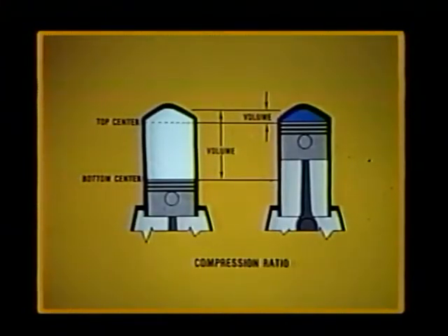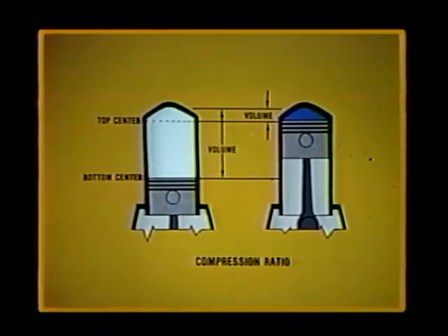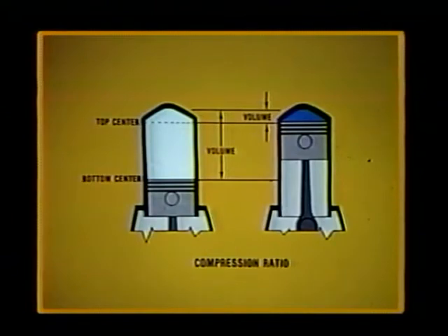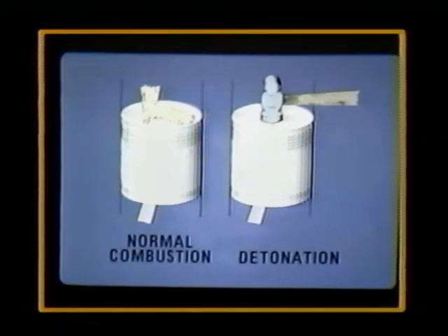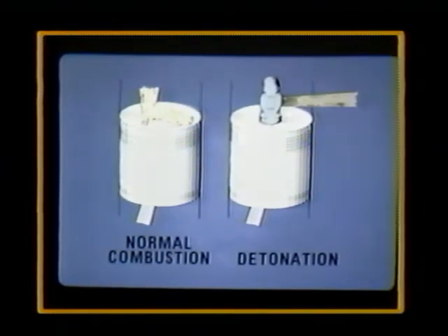The pressure inside the cylinder before ignition is determined both by the manifold pressure and the compression ratio. This is the ratio of the volume of the cylinder with the piston at bottom center compared to the volume of the cylinder with the piston at top center. The cylinder pressure is limited, however, by the detonation characteristics of the fuel. This means if the pressure gets too high on the mixture during combustion, it will explode or detonate rather than burn smoothly. This explosion produces extreme pressure inside the cylinder, causing damage to the engine.